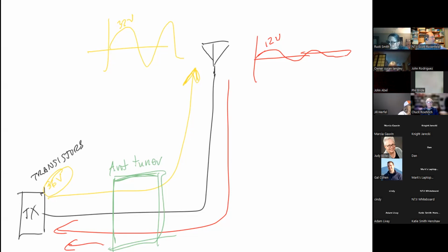If you're going to use a standing wave ratio meter, you want it as close to the transmitter as you can put it. Now, we are all lucky in a lot of ways. If we are dealing with something other than a handheld radio, this will probably not happen, where you blow up your transistors. With a handheld radio, you'll still blow up your transistors and destroy your HT. For most larger radios, they do something called fold back. The reason is that they have standing wave ratio sensors built in.